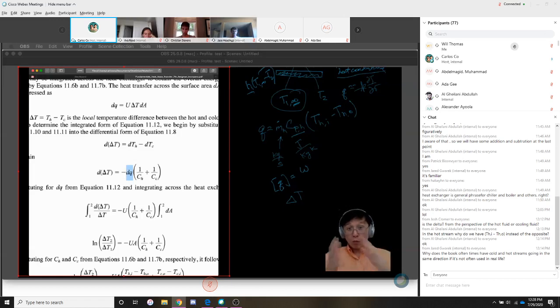If you're solving this problem without looking, what would trigger you to want to do that? The reason is that you know the problem has to depend on your heat transfer coefficient. Inevitably, the kind of heat exchanger it is, water, water, or steam, the value of U has to come in.